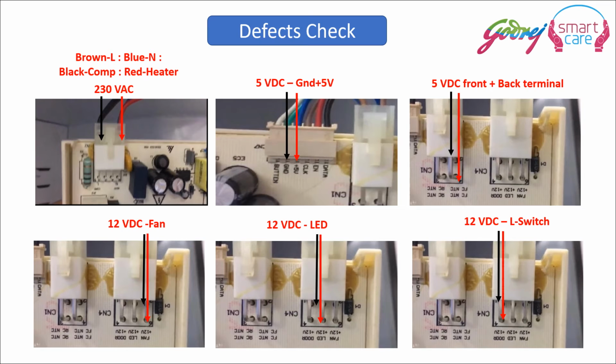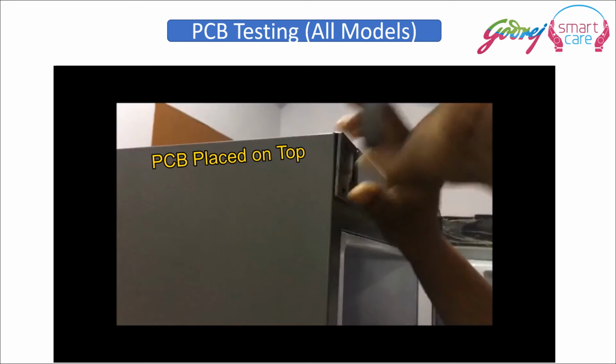And then here for the fan, the inside and outside leads will give the 12 volts DC outgoing to the fan. Similarly, at the center we have the LED inside and outside pins. Between those 2 pins we get 12 volts DC, and on the next side we get 12 volts DC on the inside and outside pins, which is going out to the door switch.